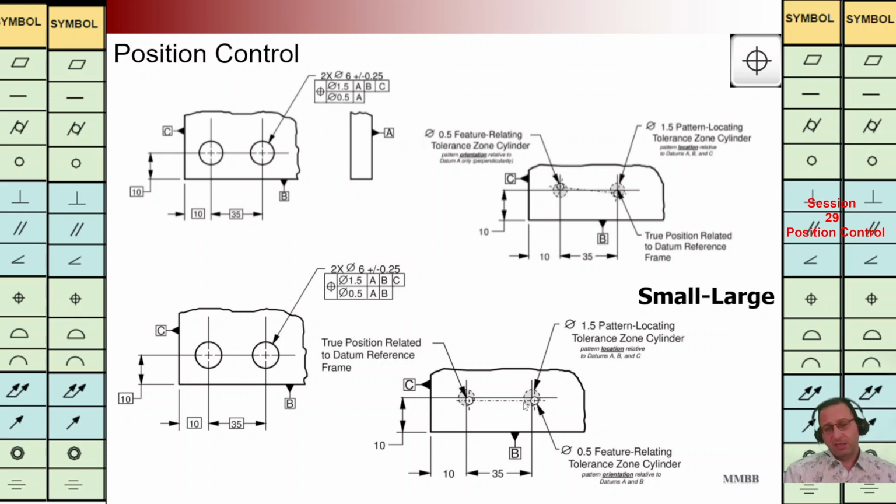It means this pattern, this dashed line, cannot be rotated with respect to B. Whenever we are going to have this small cylinder, somehow it means we are going to have this offset with respect to B. It should be in that small cylinder for both of them. And center to center of these two small cylinders should be parallel to B. It cannot be rotated. Somehow we are going to control this pattern. We are going to have more limitation when we add this reference plane B here.